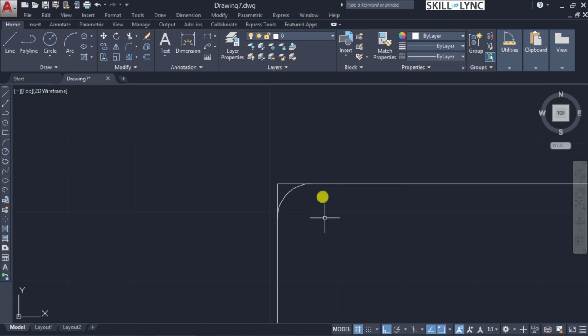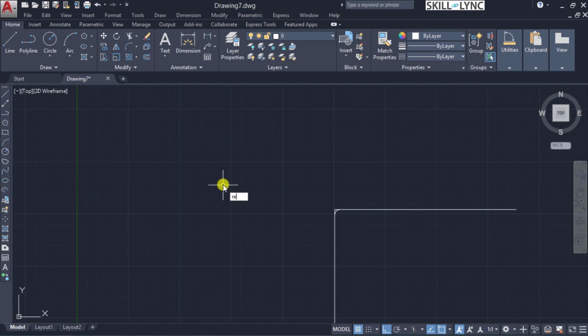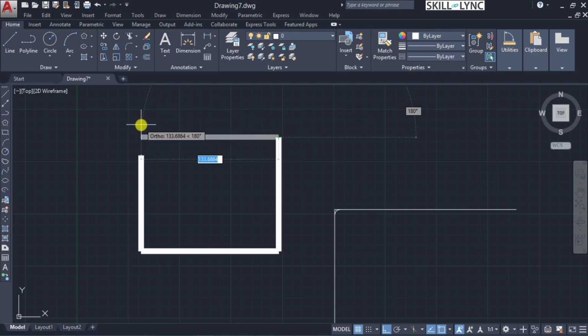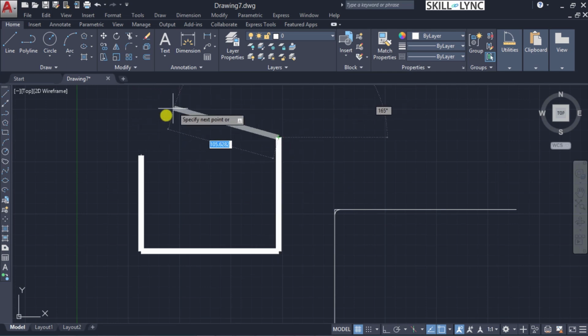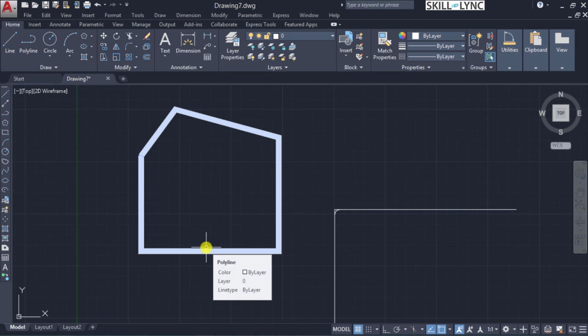So next, we can also apply this to a polyline. So towards that, let us draw in a polyline segment. So consider it to be something like this. The reason why it is ticked is because the latest command we had used for polyline, during the polyline demonstration, had a width of this. So if you want to edit it, then you can use the pedit command.